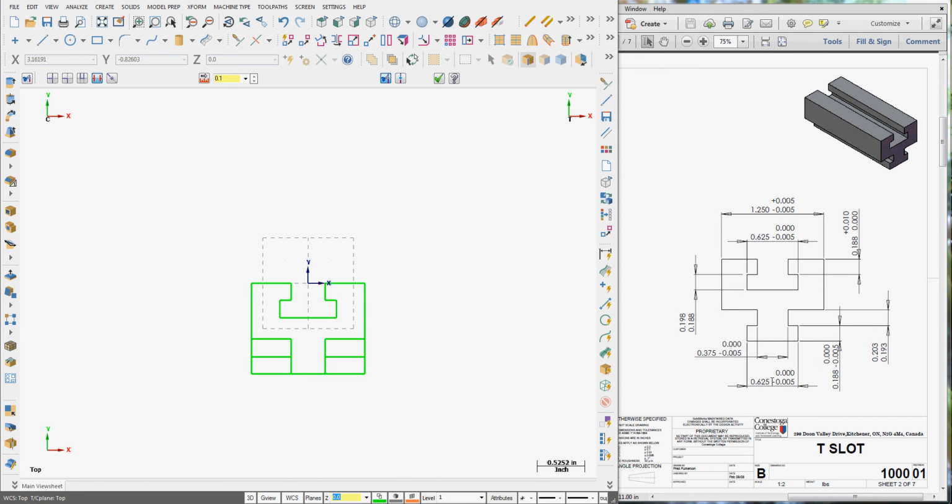So down on the bottom, this is also 5/8 about the center. So I'm going to stick with trim, but this time I'm going to use to point. So I'm going to trim that line down to the bottom. And I'll trim this line to the bottom. And again, I'll go back into my divide command to fix it up. So we can see that this line goes. This and this will go. This goes and this goes.